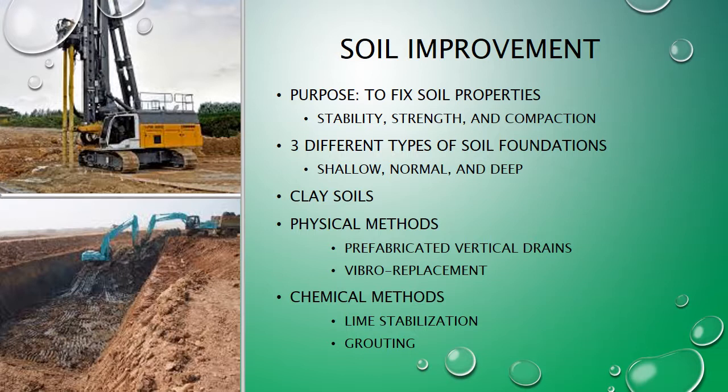For further specification, the methods discussed will also be limited to those most commonly used to treat clay soils. Some of these methods will involve physically altering soil by means of drains or vibro replacement. Others will involve chemically altering soil by mixing in additives such as grout or lime.